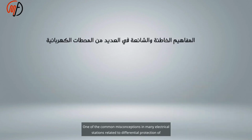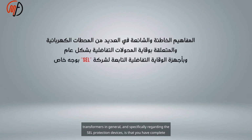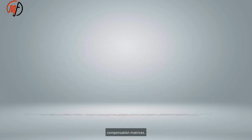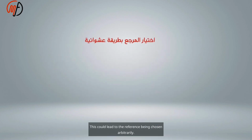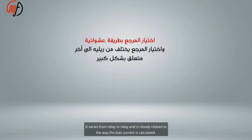One of the common misconceptions in many electrical stations related to differential protection of transformers in general, and specifically regarding the SEL protection devices, is that you have complete freedom to choose either side of the transformer as a reference for the angles when determining the compensation matrices. This could lead to the reference being chosen arbitrarily. It varies from relay to relay and is closely related to the way the bias current is calculated.